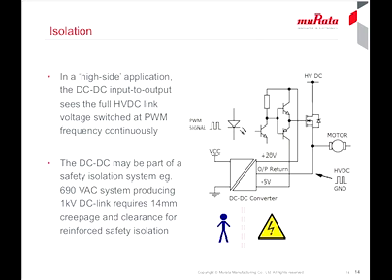In a later webinar, we will look at some examples of stress testing to show the differences between general-purpose DC-DCs and the gate drive versions. Even if the DC-DC has isolation rated for high continuous voltages, if the DC-DC is part of a safety isolation system in the end equipment, it will need a level of safety certification. This may limit the voltage stress allowed.